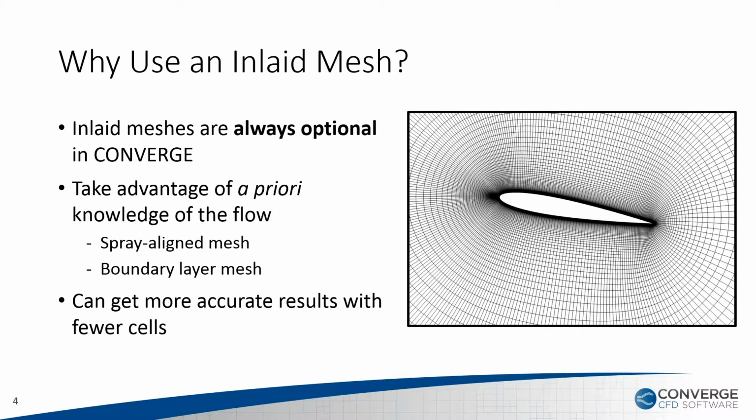I want to mention that inlaid meshes are completely optional in CONVERGE. So say you had a case that you've been running in CONVERGE with older versions like 2.4. Those cases will run perfectly fine with 3.0. However, with 3.0, the user now has the option to specify a grid of their choice to cover a certain portion of the domain.